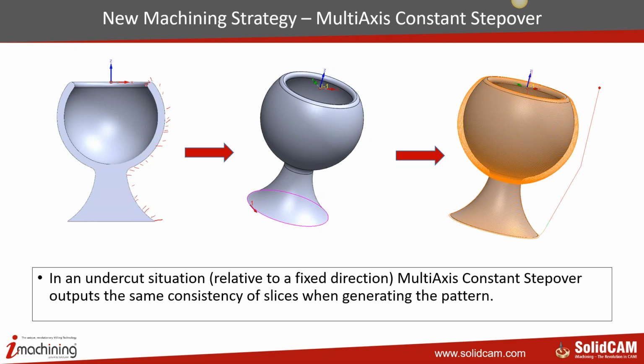So even on this fillet, you will have a constant toolpath, and once it goes inside also there will be a constant toolpath, and once it comes to the center it will retract up. So you'll see that there is one entry and one exit. All this toolpath now has a consistent, constant stepover between the passes.